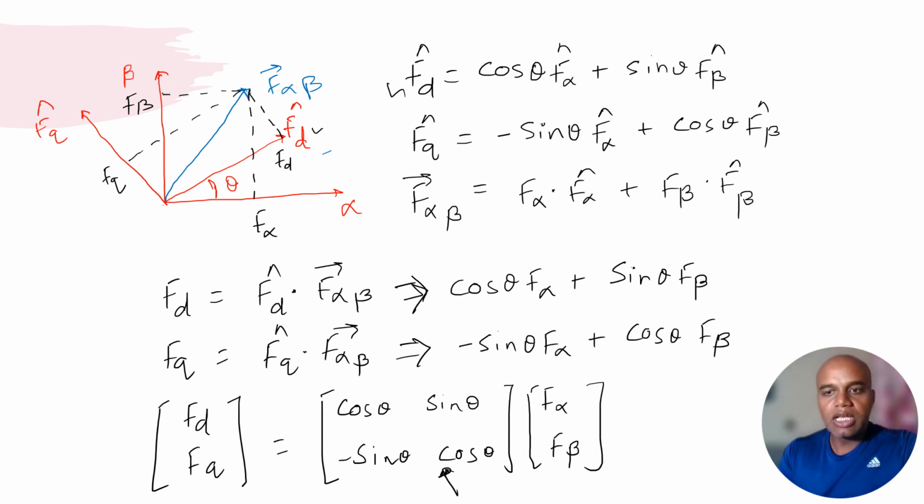Before giving this control signal back to my motor, we need to perform the reverse transformation. First we need to perform the reverse Park transformation, which will convert these DQ values again into the alpha beta frame, and then the inverse Clarke transformation, which will convert alpha beta values into the three-phase ABC values. All these values we can then give back to my motor by using the PWM inverter.